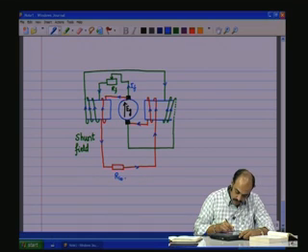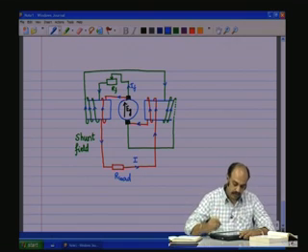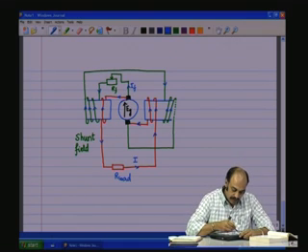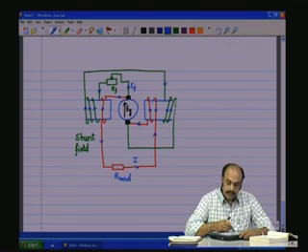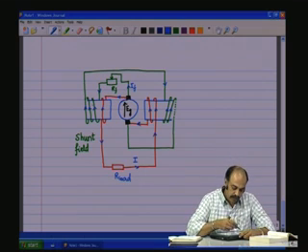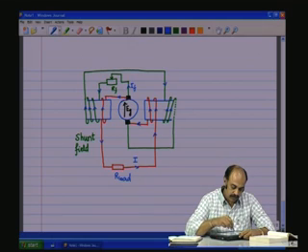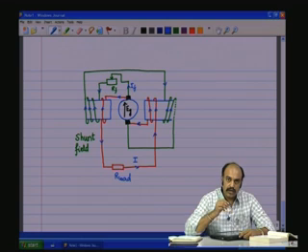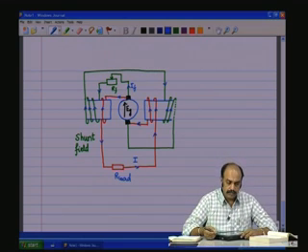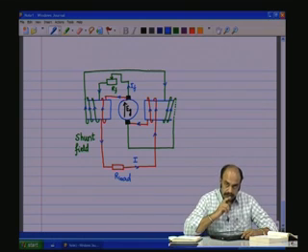This is R load and this is current I, whereas this was IF. If the number of turns here is so designed such that it cancels out the load component of the shunt field winding flux, then the flux in the machine will be a constant, dependent only on EG, like in the case of the separately excited machine. So, this is a compound machine.